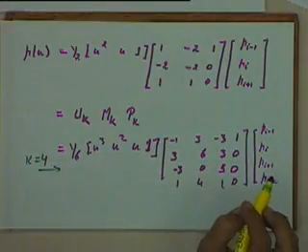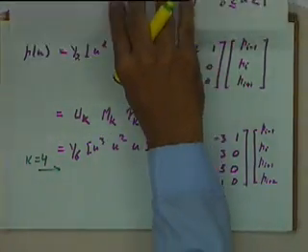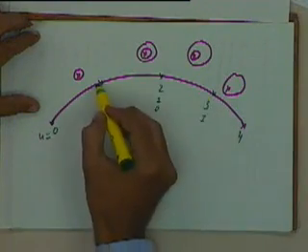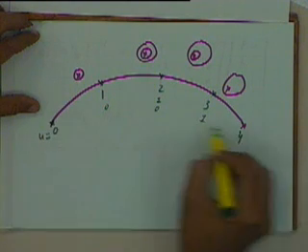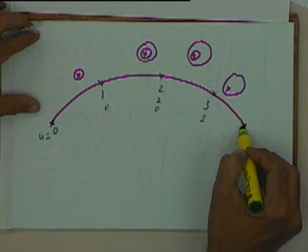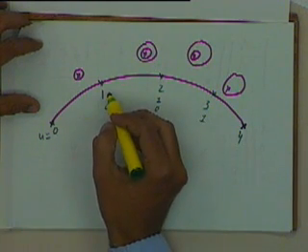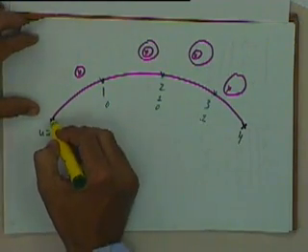What that basically means is that my curve has one formulation in this range and this range, but at the ends the formulation is slightly different. That's basically because my shape functions for this point and for this point, the blending functions, are different. And if we want to use the same blending functions, then my curve might not start from here, but it will start from some other point.